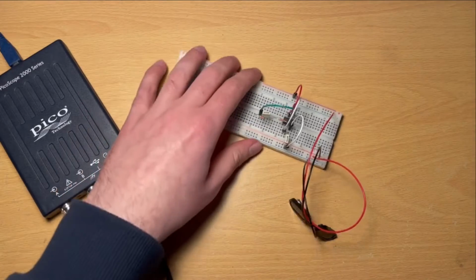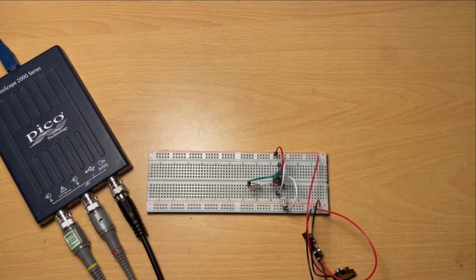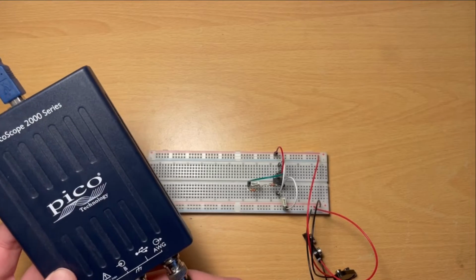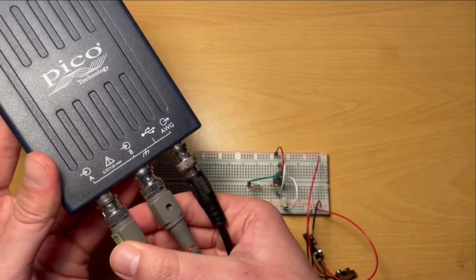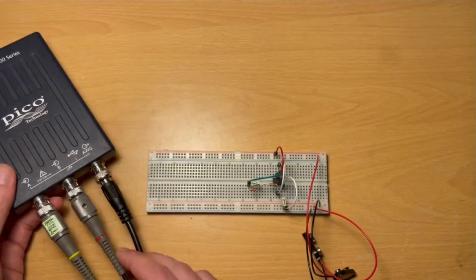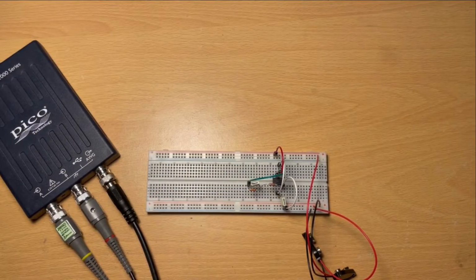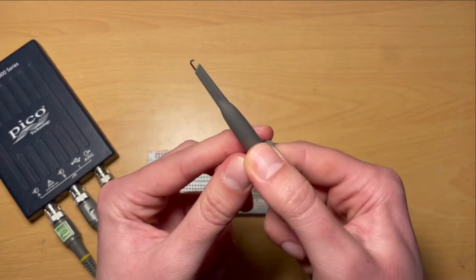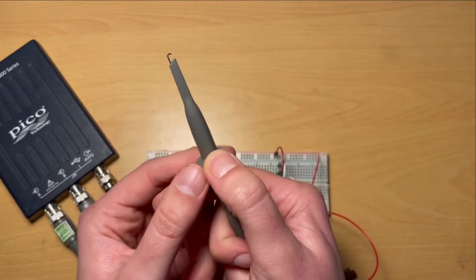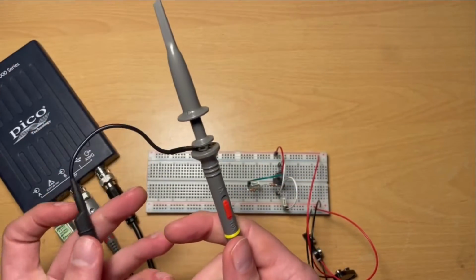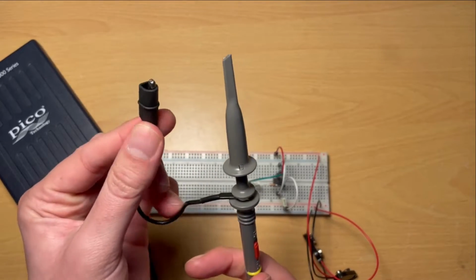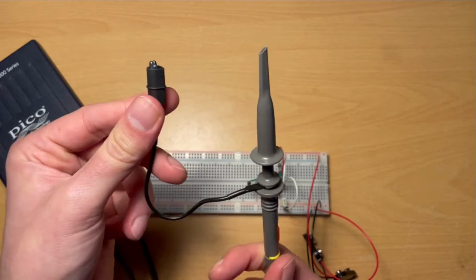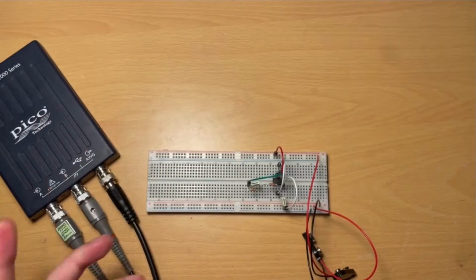If you're not familiar with oscilloscopes and leads and connections and stuff like that, very simply, we have these scope probes which are connected coaxially like this with a sort of twisting locking mechanism. And the other end of the scope probe looks something like this. We've got a retractable sort of spring-loaded hook mechanism that we can use to clip onto components for measurement purposes. And those measurements are made with respect to ground or to zero. And so this is our ground connection as well, which is sort of tied on to each probe.